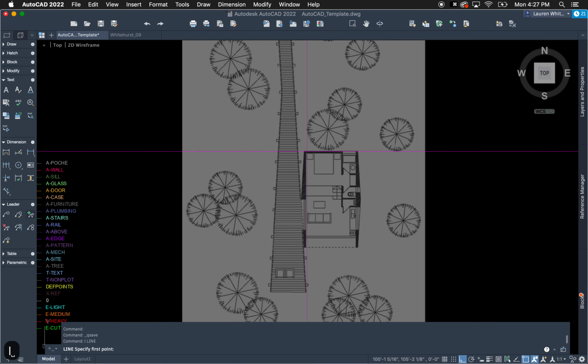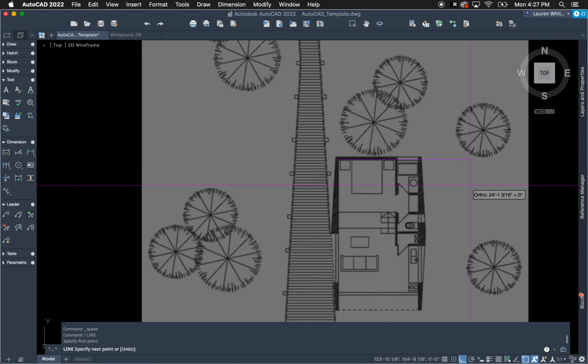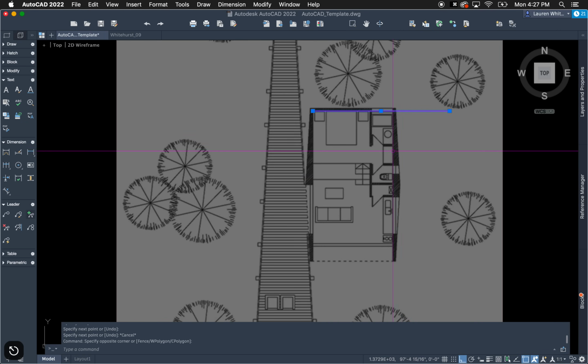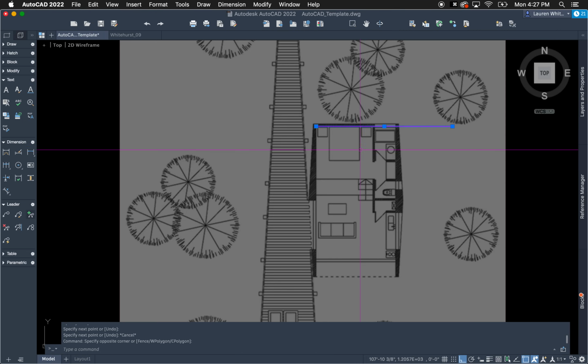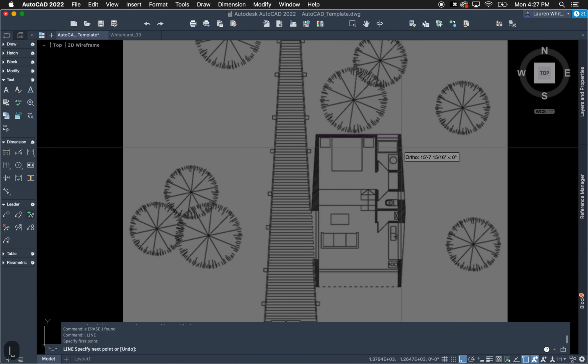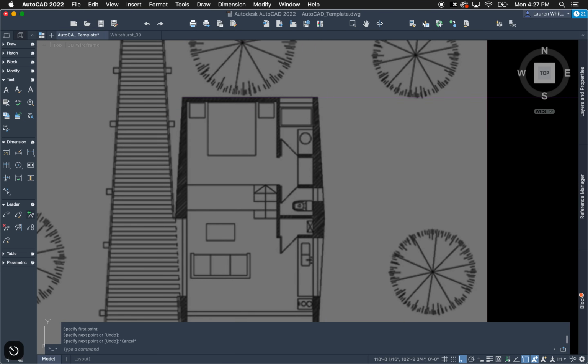Then, to draft, it's pretty simple. Normally I pick a spot and I start. If you're drawing something with known dimensions, it's a good idea to work from the big dimensions inward to smaller dimensions. But since I'm just tracing this image, it doesn't really matter how I go. Again, you're drawing the lines by typing L, clicking, and then clicking again. I can click past the lines. I like doing that and then coming back and trimming rather than having to line up exactly.